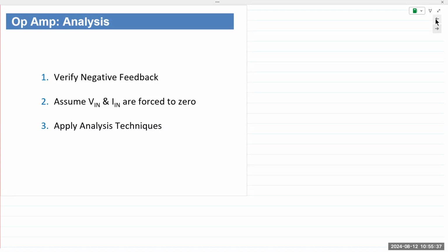When we perform our analysis, remember, we are using an op-amp as an off-the-shelf building block. The op-amp by itself has some properties. Then you connect a few other components, resistors, capacitors, even inductors to it. The circuit is now different, and that circuit itself will also have some properties. So key thing, keep that in mind. They are not the same thing.